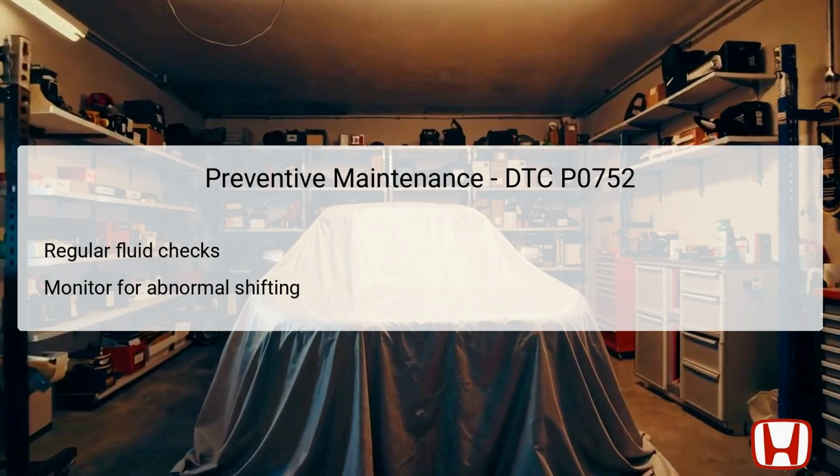This fluid serves as both a lubricant and hydraulic medium within the transmission, and degraded fluid can lead to various shifting issues. Additionally, owners should monitor for any signs of abnormal shifting behavior. If any irregularities are detected, they should prompt immediate investigation to potentially prevent costly repairs in the future.